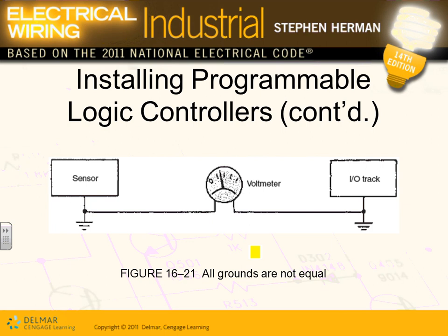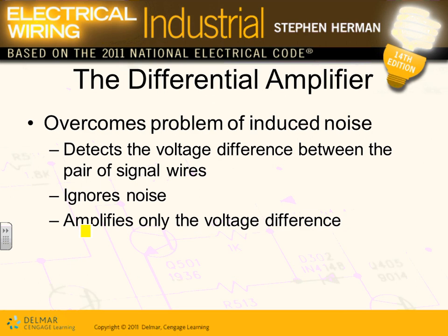The other thing, guys, you have to also ground the track, the input-output track. Everything, the sensors, everything is grounded to the same point, so you don't have a voltage difference between them. Okay, so we ground them, we keep them short, we isolate them from the power line, and we shield them. There's something called induced noise.